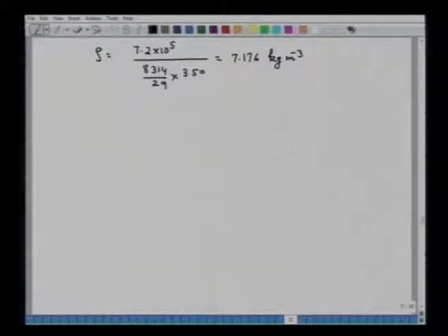Now, I can substitute into the expression. So, this m will come out to be equal to 0.33 kilogram per second, and this is the answer for the flow rate of air. That is how you can see, by installing a manometer and orifice in a pipe, one can calculate the flow rate of air.